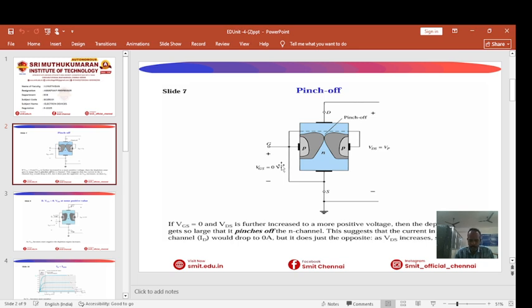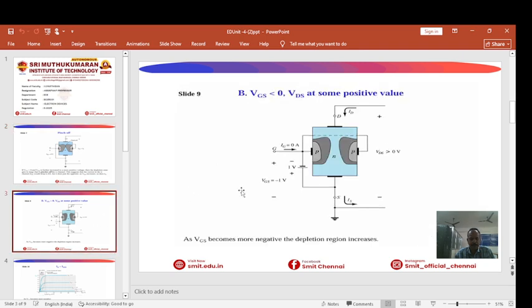The gate and channel form the PN junction. Normally, these PN junctions are reverse biased. Source supplies the electrons to the channel. Drain collects the electrons after they travel through the channel. So the gate controls the width of the conducting channel. Since the gate junction is reverse biased, almost zero current flows. That is why JFET has a very high input impedance and low power consumption.